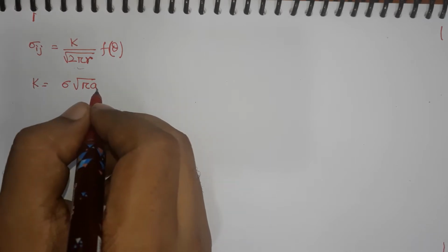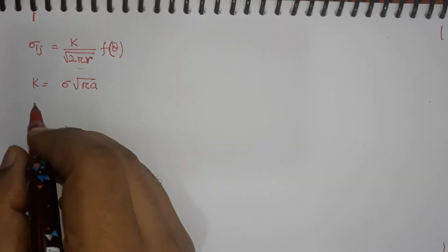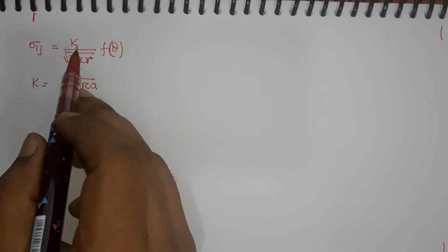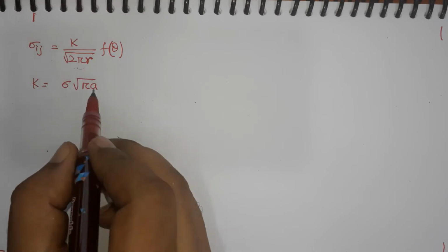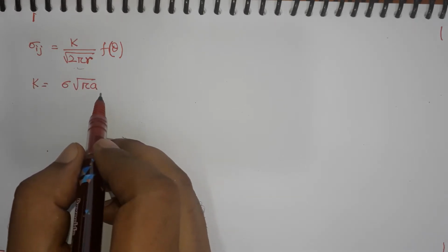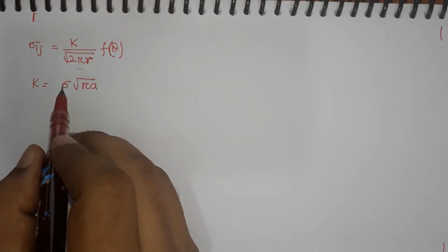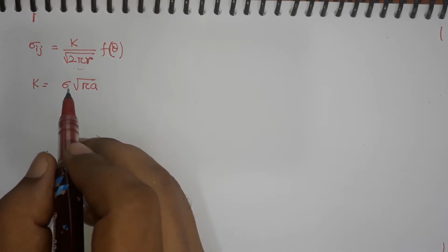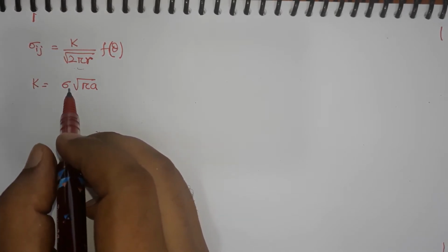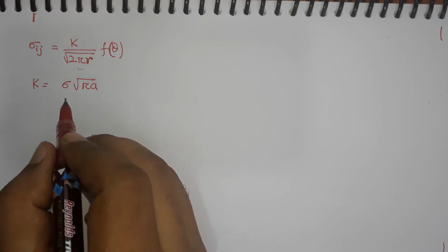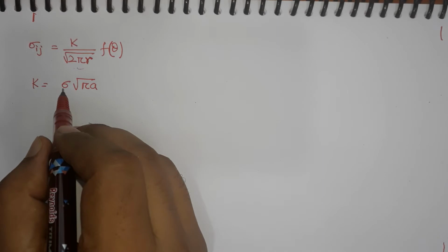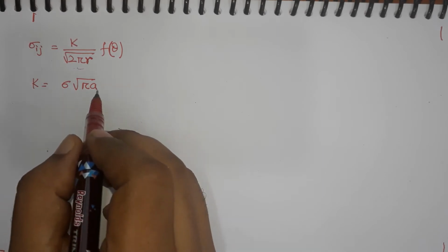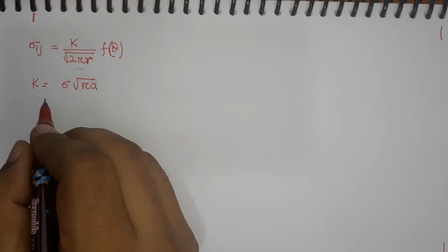Now the thing is that this stress intensity factor can have a critical value. So, depending upon what is the crack length and how much stress you have applied, stress will have some value. And apart from the application of stress and crack length, it also depends upon the geometry of the specimen.